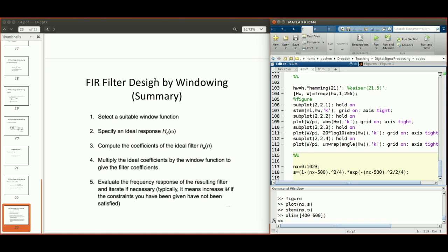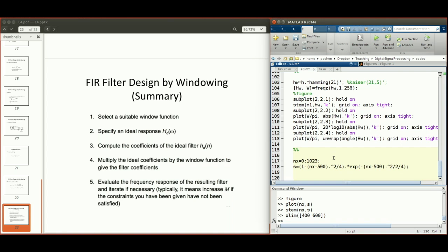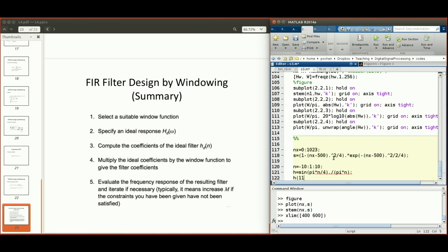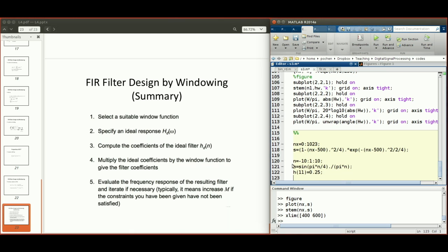So now let's try to construct this time domain FIR based on a boxcar time window, right? So n goes from -10 to 10, right? That's gonna be the horizontal axis of the filter. And then h, that's gonna be our time domain response of that low pass filter. So that's the horizontal axis of the filter, time domain representation of the filter, and then that's the sinc function.